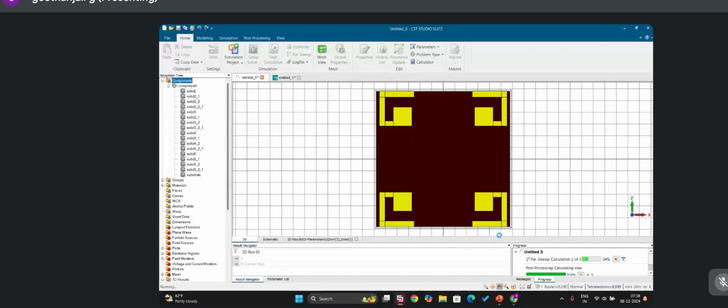So you have to incorporate the lumped resistors in the design, and you have to separately design the bandpass FSS for the transmission characteristics, and you have to add the resistive FSS and bandpass FSS with the help of an air gap to achieve the frequency selective rasorber. So it is also an interesting topic similar to FSS.